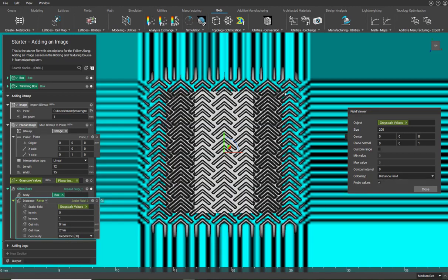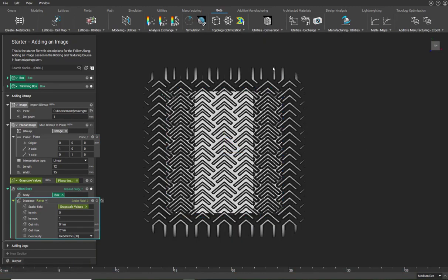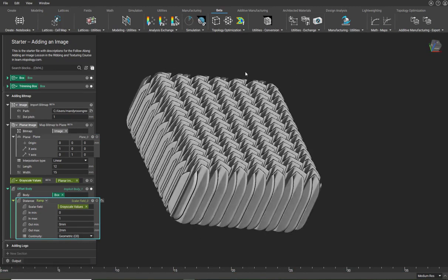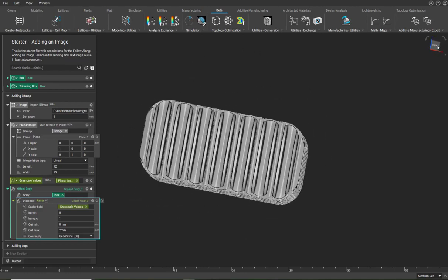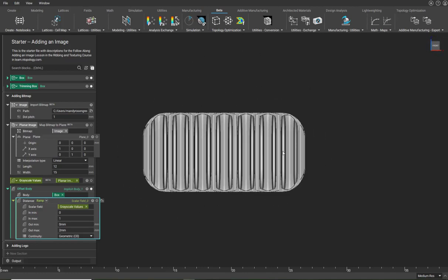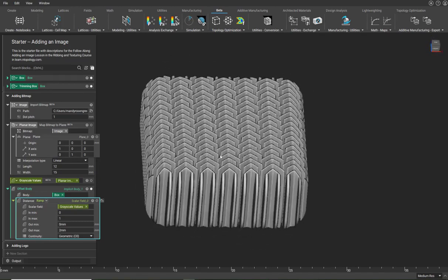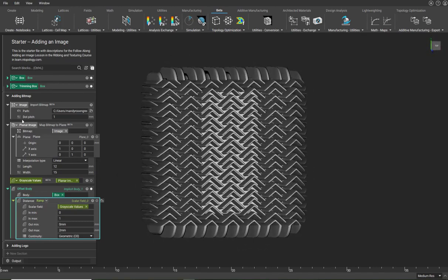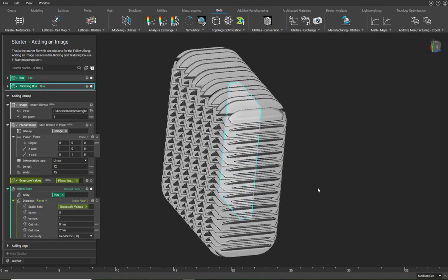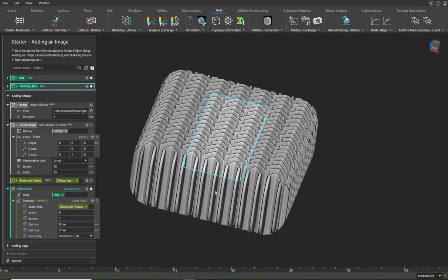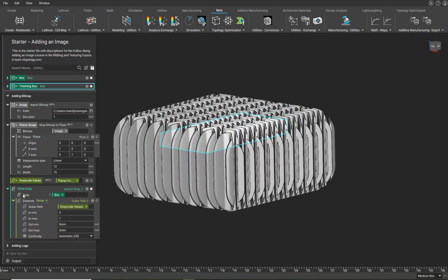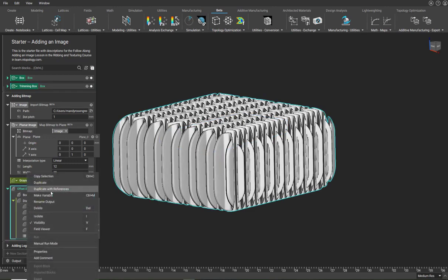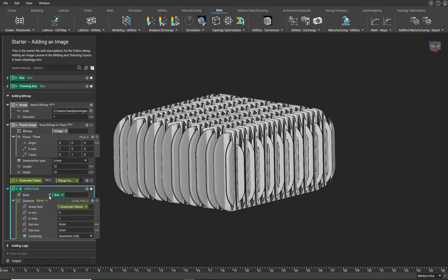So we can see I am seeing that design now as a field, and it has its offset 2 millimeters above, below, and all around. So that's why we needed that trimming box. And I have that trimming box shown, so we'll actually only keep anything that's within there. So you can play around with how much of that outmin, outmax you actually want. But I'll make this a variable, label this 3D texture,